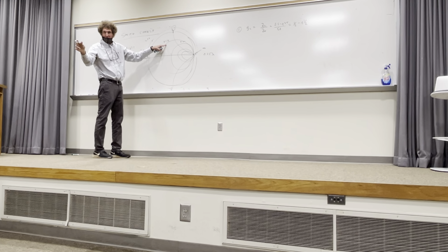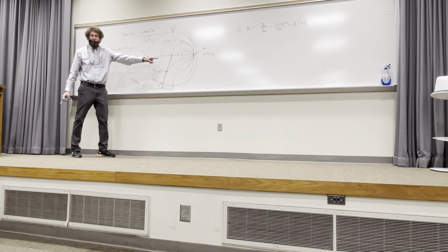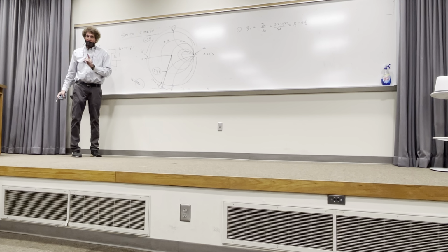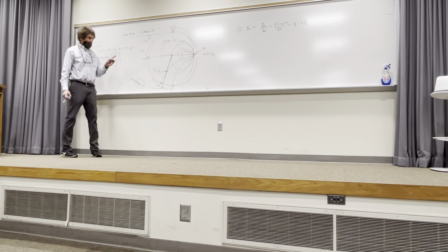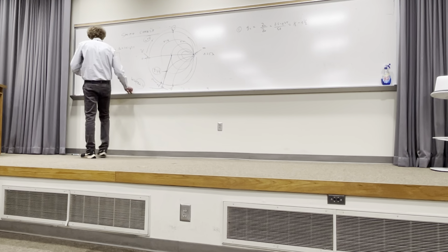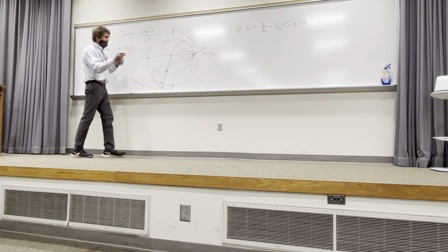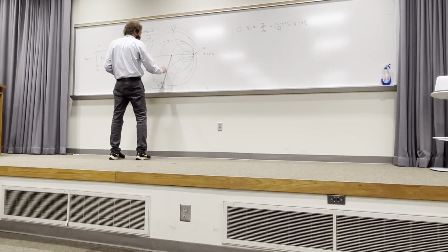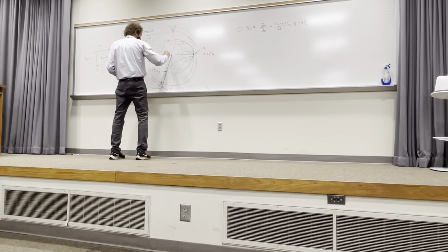So now, this is important. All right? We're here, and we're going to move away from the load to the generator, towards the generator. We're going to move a tenth of a wavelength. Are you with me? Because that's what the problem said before, right? So now we're going to move. Now listen. Oh, I didn't say this. Take your compass and put the pointy end right there, and the sharp pencil tip right there, and make a circle of constant radius. So it'll be something like this.